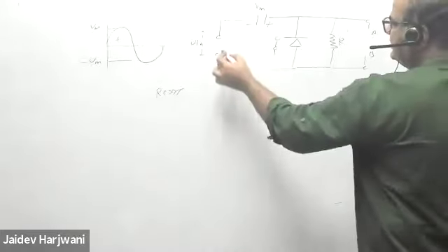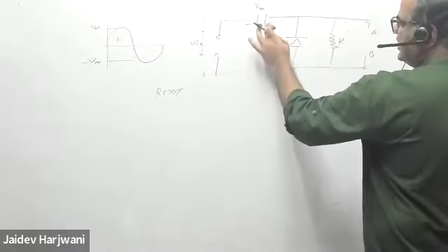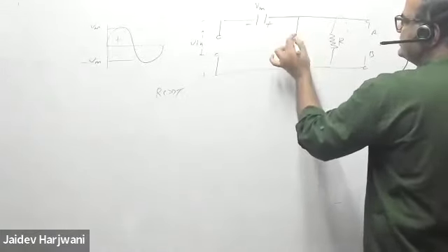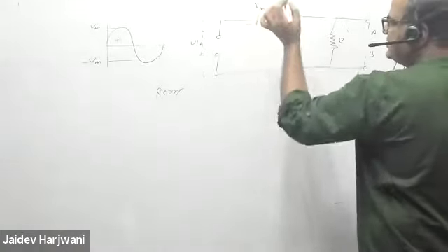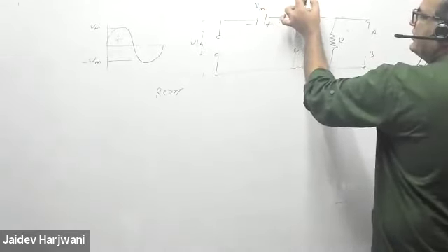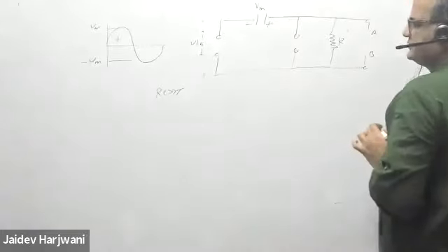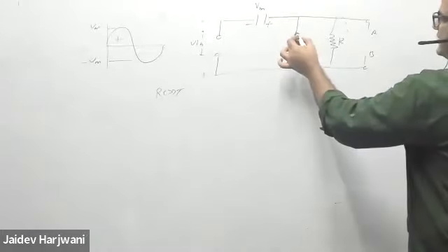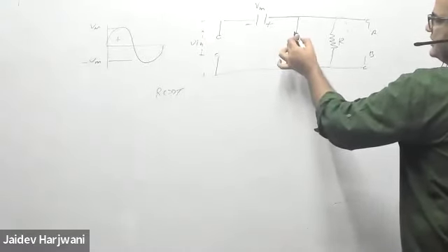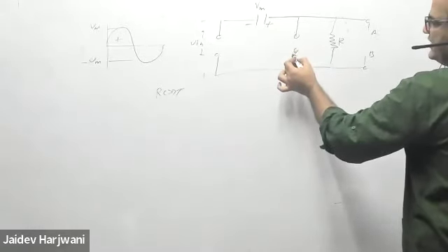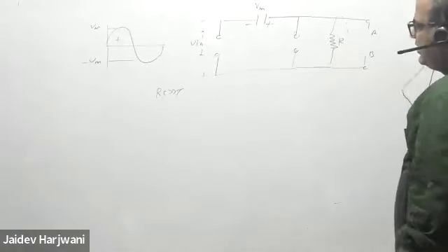Now what will happen? The capacitor will charge through this diode in this direction. Once it is charged, the diode becomes reverse biased, because now the minus plate is connected to the plus, and this Vm is always greater than the V input sine wave. Practically it is always in reverse bias. Suppose here it is plus 5, and here the input varies from 0 to 5; so it is always reverse biased.